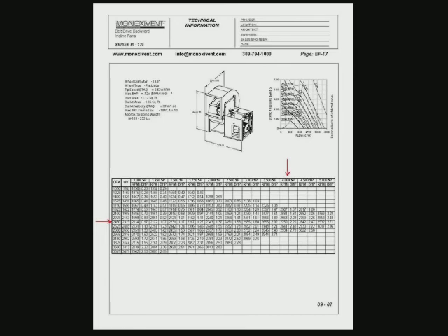Okay, so next and finally, we have to select a fan for this particular application. You saw earlier on my initial design sheet, because I knew the system was going to be 2400 CFM, so when we look at the actual performance chart for this fan, it's our BI 135, 13.5-inch wheel, backward inclined centrifugal vent set. When you look at 2400 on the CFM line versus 4 inches of static pressure, you can see those numbers come together right down the heart of the performance curve.